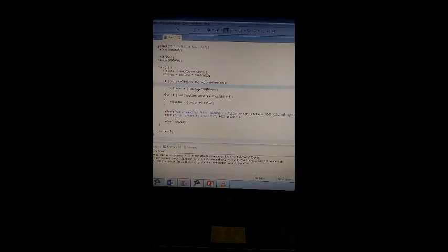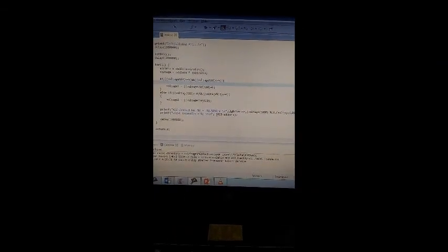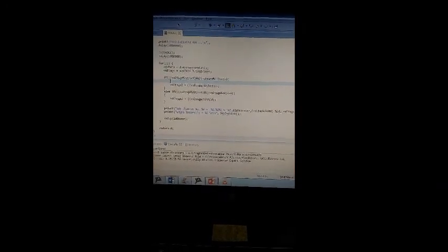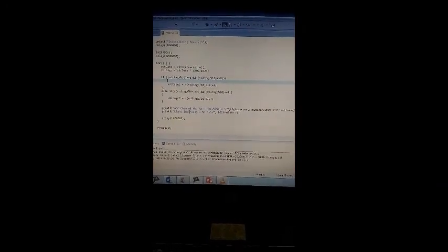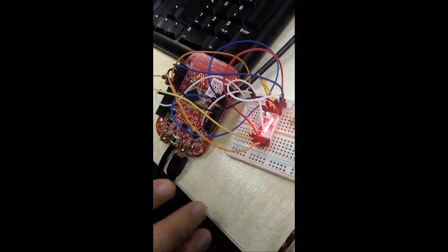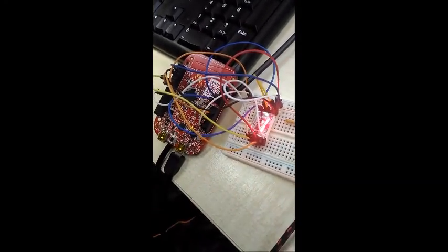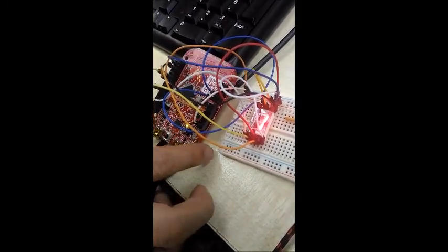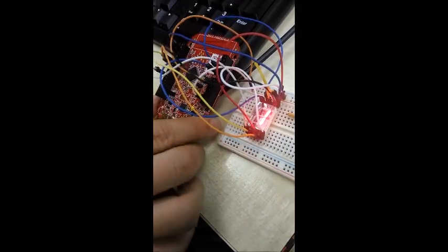And right now we will continue with the previous explanation of 1023 minus ADC data, which is for the light intensity. So since we are doing it such that the more the light intensity, the higher the reading. So right now at the normal light intensity, the room light intensity, it will be 1.